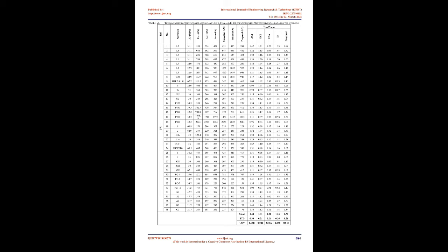Therefore, to evaluate and assess the applicability of this proposed equation for NSC, a sample of different slabs tested by different researchers with compressive strength less than 69 MPa were used. The prediction of shear strength for normal strength concrete, NSC, specimens by proposed equation and different codes are calculated, and the means, standard deviations, and coefficients of variation are given in Table 6.